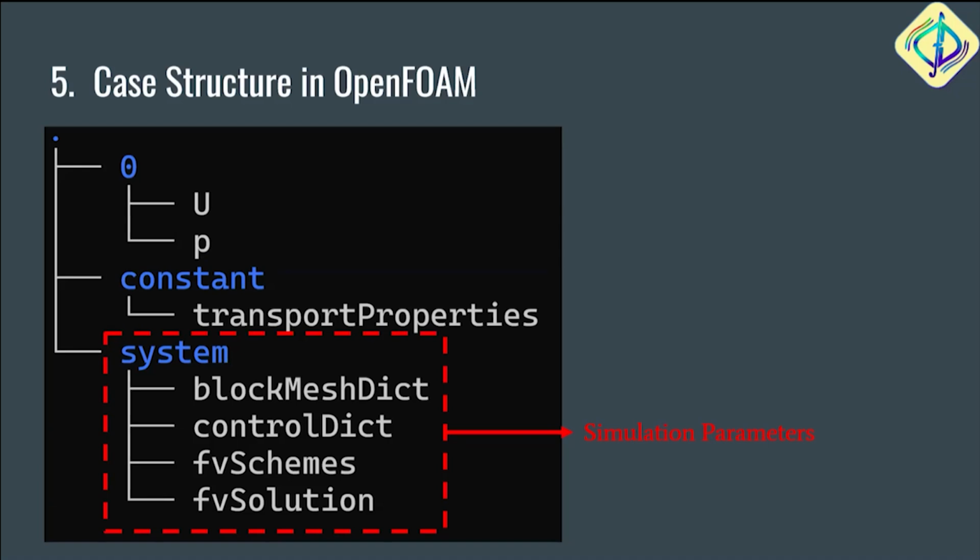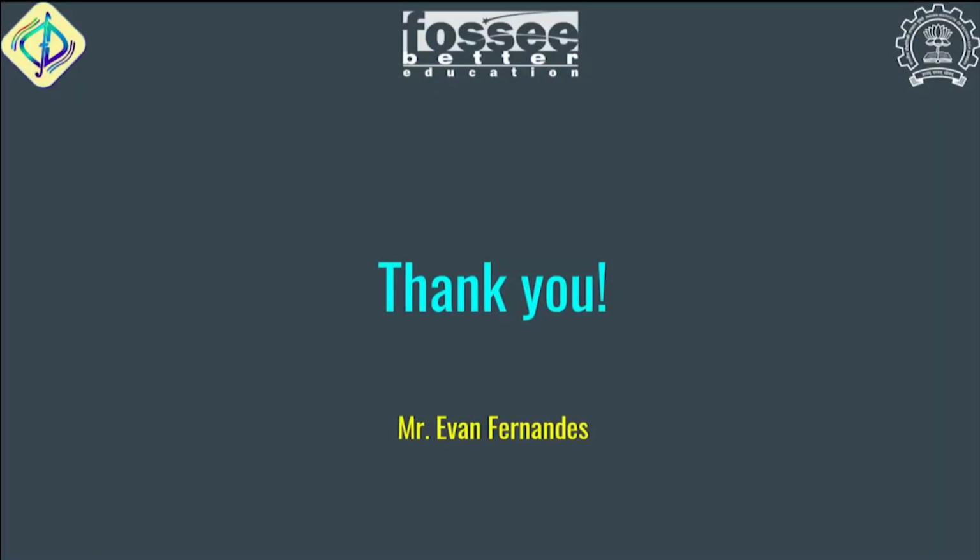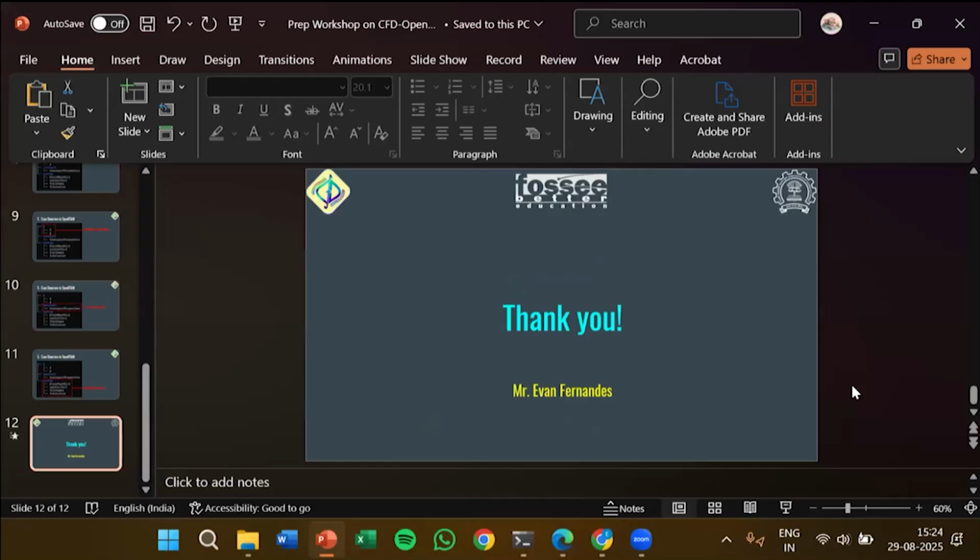And then you have your fvSchemes and fvSolution. These are where you will change your relaxation parameters. If you have to introduce any of the algorithms or you want to change any algorithm, if you want to implement your custom algorithms, you can always put those into these files. Okay. So this was just an overview of how your case structure should look. Now, we can start off with the installation session.